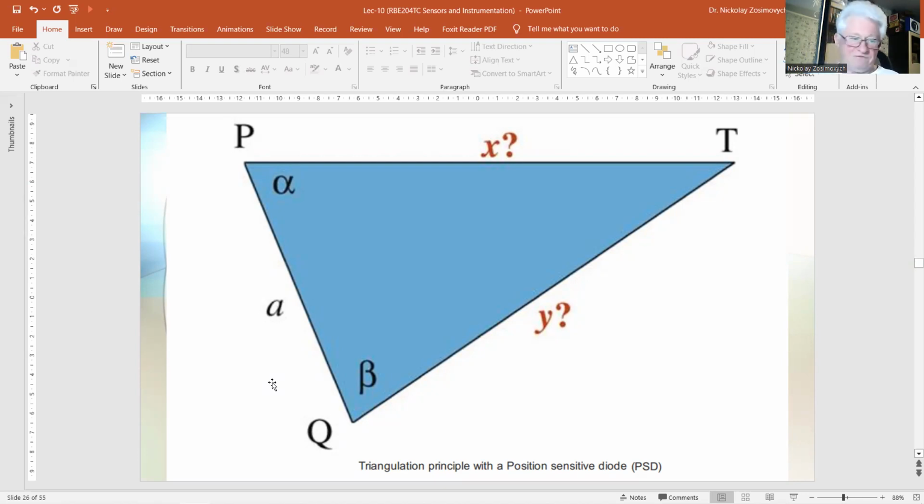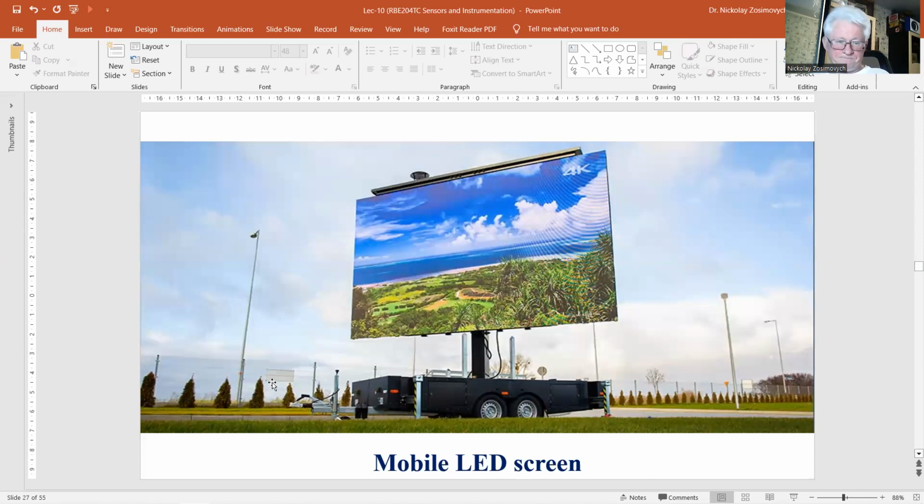Transmissive or reflective optocouplers require little in terms of interfacing when they are used to detect a digital state. Methods were discussed for using operational amplifiers to create a constant current source for the emitting part and a current to voltage converter for the receiving part.